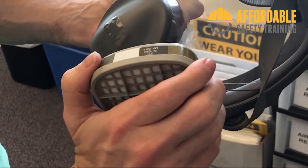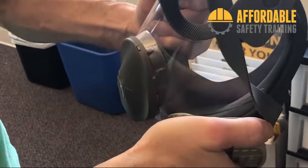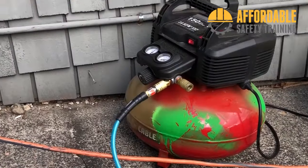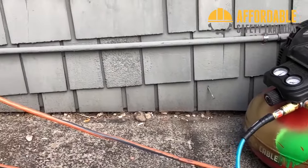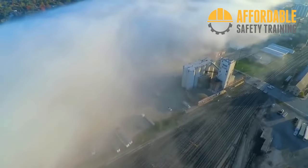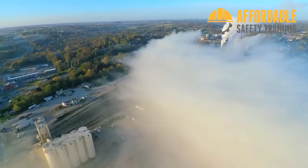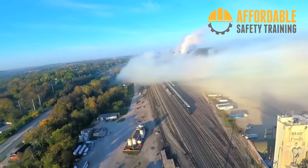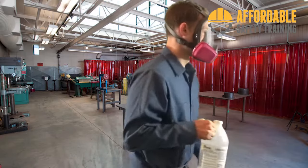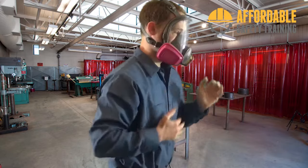Monitor the cartridges, and make sure they are changed according to the schedule, or when the end-of-life indicator requires it. For supplied air systems, monitor the air supply and the quality of air. While working, keep a close eye on the work environment. Watch for changes in conditions or atmospheric contaminants. If a new hazard is detected, or atmospheric concentrations are unexpectedly high, exit the area immediately.